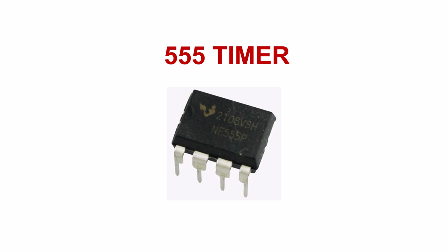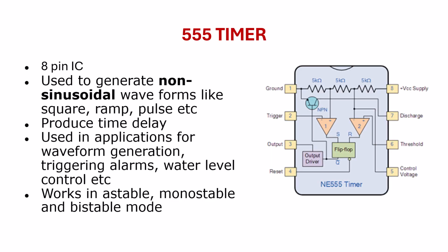Hello everyone. In this video session, we are going to learn about the 555 timer. Let me learn the basics of the 555 timer. It is an 8-pin IC. The pins are ground, trigger, output, reset, control voltage, threshold, discharge and VCC supply.